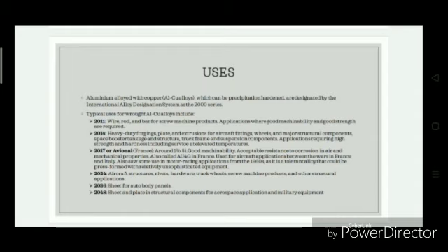2017, or Avional, has around 1% silicon, good machinability, and acceptable resistance to corrosion in air and mechanical properties. It was used for aircraft applications between the wars in France and Italy. That's one of the main uses of 2017. It also saw some use in motor racing applications from the 1960s, as it is a tolerant alloy that could be press formed with relatively unsophisticated equipment.